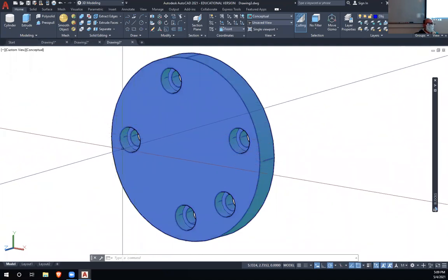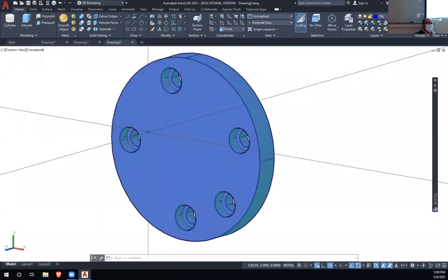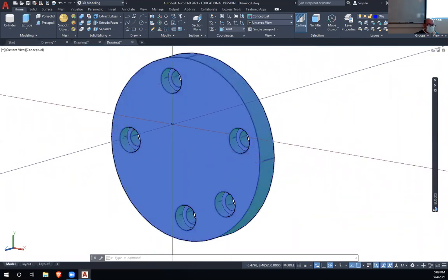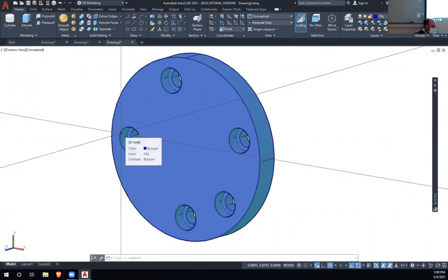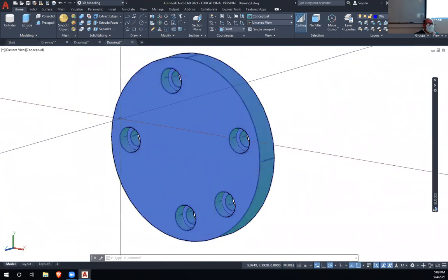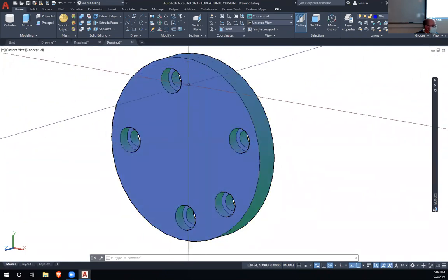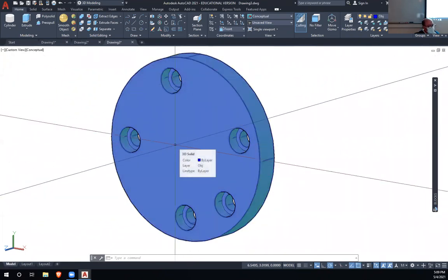So if that was just in 2D, all in the same view, you could have extruded the big one 1/2 inch, the through hole 1/2 inch, right? And then the larger 9/16 inch diameter 1/4 inch, and then subtracted them. Well, and then actually rotated and copied, rotate with the copy command, and then rotated and rotated and rotated until you got all 5. That's one way to do it.